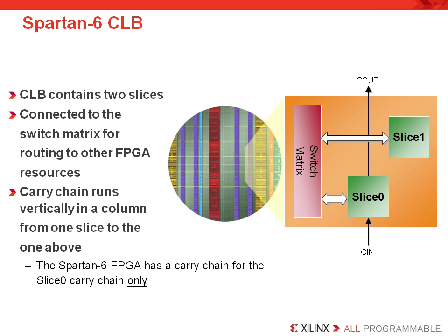All Xilinx FPGAs contain essentially the same basic logic resources, slices, which are grouped into configurable logic blocks, commonly called CLBs. These contain combinatorial logic and register resources. As you can see from this picture, there are a lot of CLBs on this die. While each device family is offered with a different number of CLBs, determining which density is right for your application often requires you to at least synthesize your design before choosing an appropriate density of FPGA.